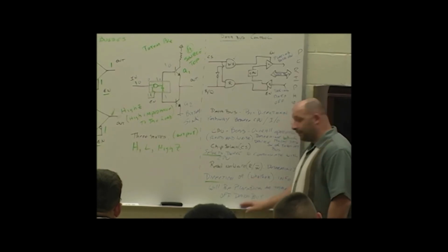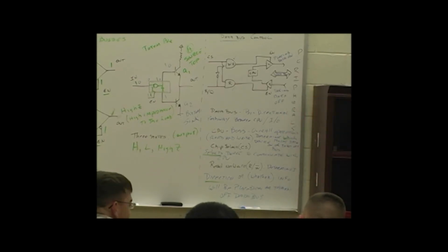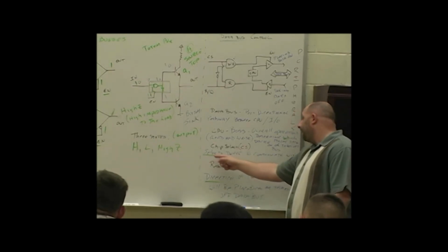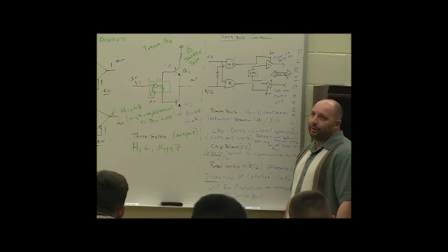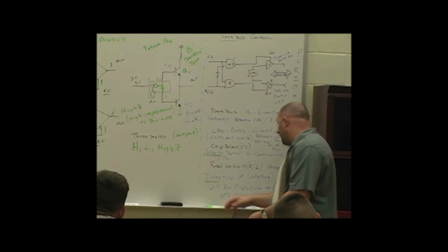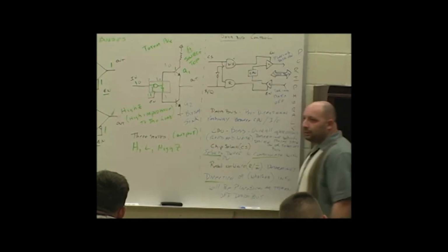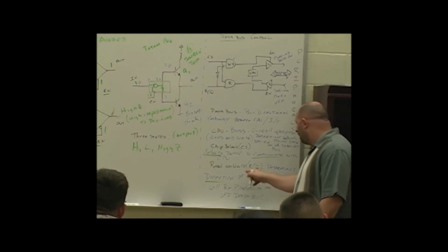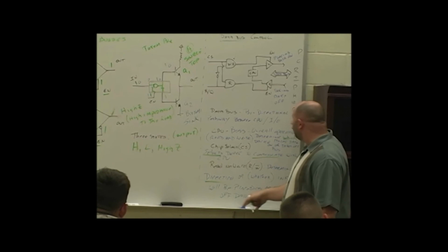Okay. Don't let these definitions kick your butt, because I'm trying to help you by pointing out key words. Chip select, it's got the word select in it. Selection device. What device? Peripheral device. I need to talk to the CPU, so the chip select signal comes back high. I need to communicate. Read not write controls the direction of the data.